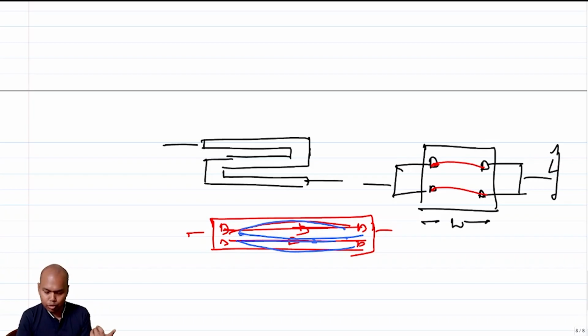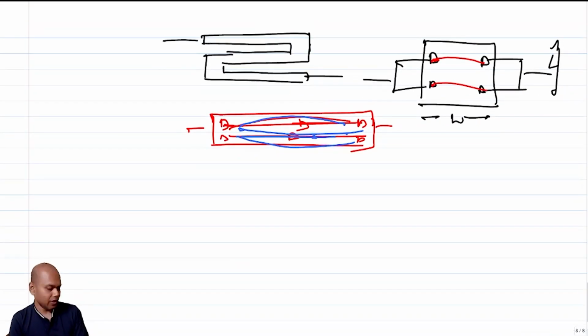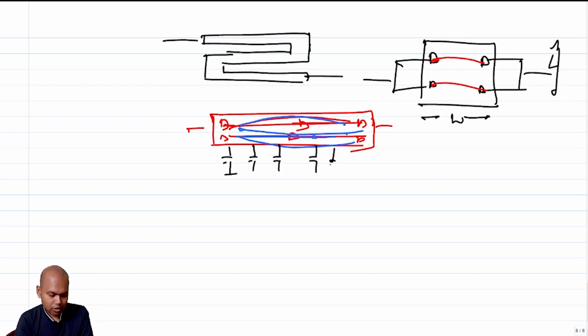And the other thing that you should take care of, if the very high frequency performance for a resistor is also important, is that you should be aware that these are all distributed resistances, right? This resistor is also sitting on a substrate, so you are invariably going to have capacitance to ground. So effectively, no resistor is a resistor. The resistor is a distributed resistor.